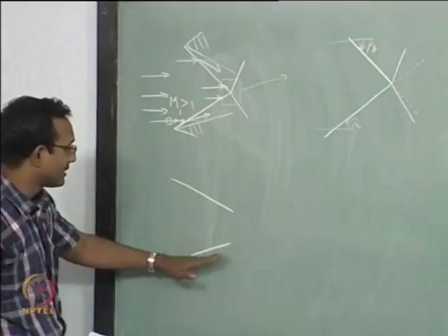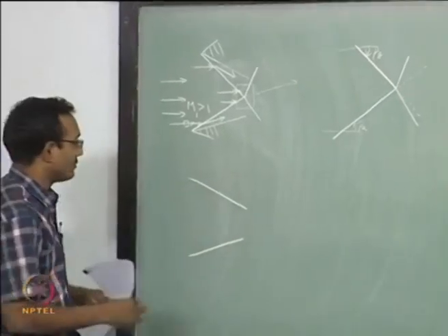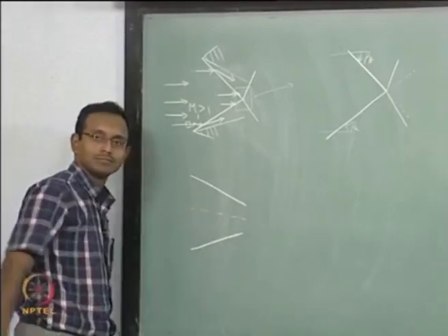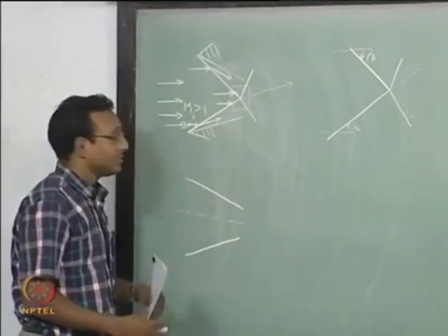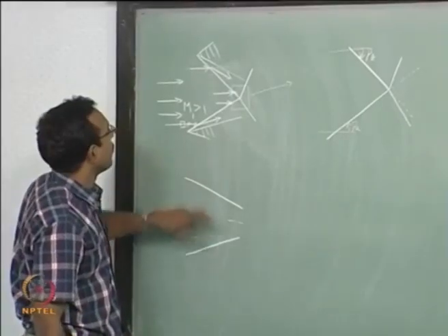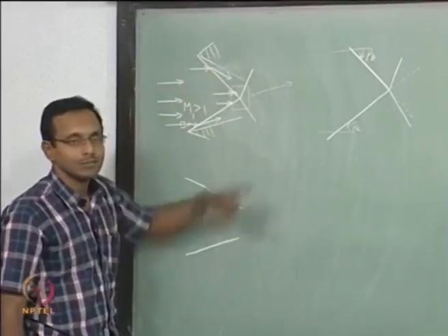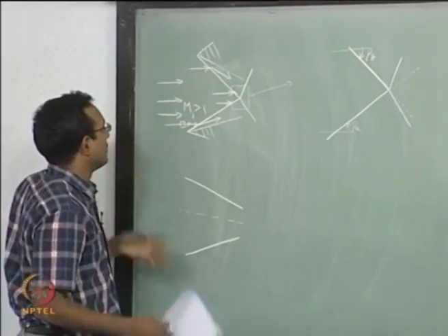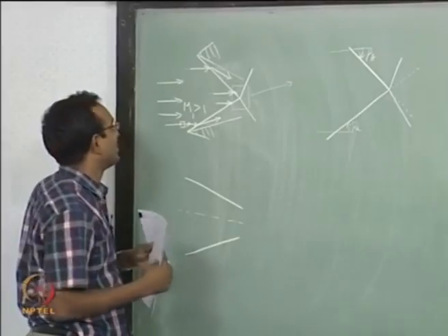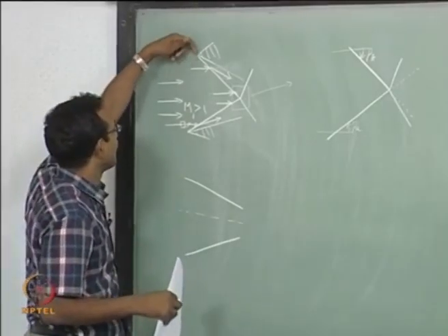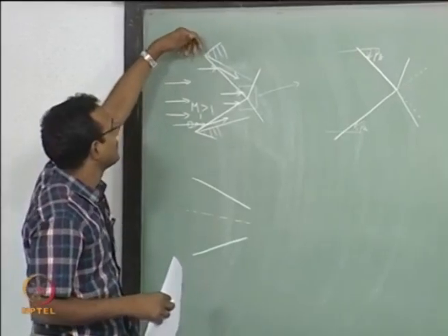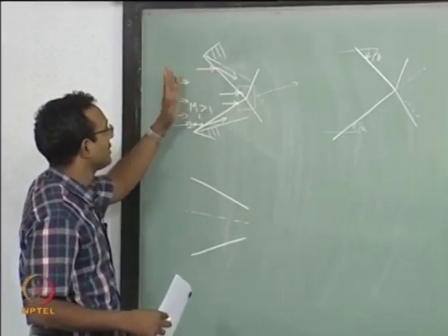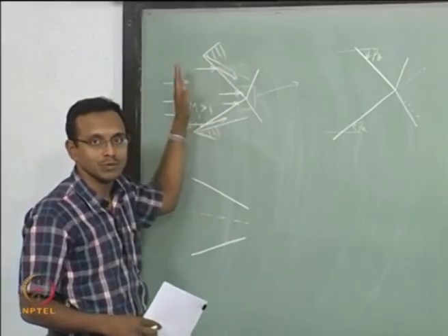Okay? This angle is less than this angle, which means if I draw a center line for this duct, it is eventually going downward. Okay? Which means these two bodies together want the flow overall to go slightly downward. So basically we go back to our piston analogy. We always keep switching between piston analogies. I can imagine these two flows as if there is one piston coming from that side, another piston coming from this side, and they are both sending shocks as my piston cylinder is moving this way.